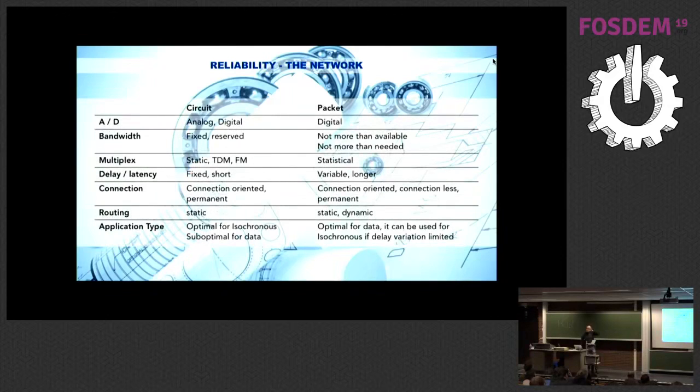Interesting, you can dive into the difference a little bit more. You have circuit-based networks, like our SDI, and you have packet-based networks, specialized for data. But this is the important part here: we can move towards that sort of network for professional media. The only thing we need to take care of is the packet delay variation.